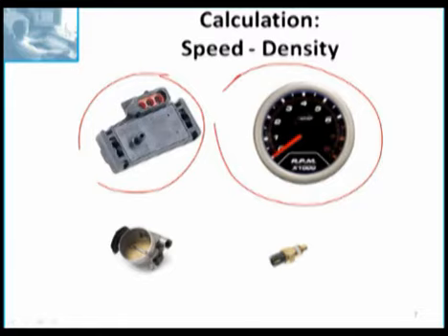Vacuum leaks affect a speed density car differently than they do a mass airflow car. So you want to keep in mind that a vacuum leak would probably just increase the engine speed at idle, and may show up more under the idle control solenoid PID than it will under the fuel trim PID. And finally, to eliminate this MAP sensor as your cause, you do want to check it key on, engine off, and snap the throttle and verify that it responds.